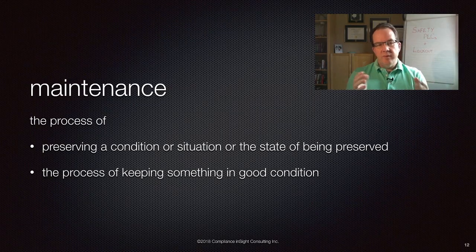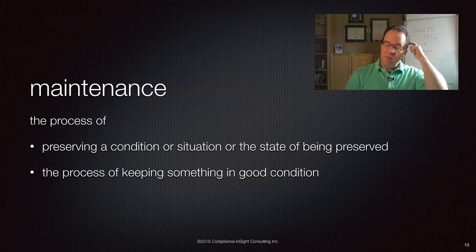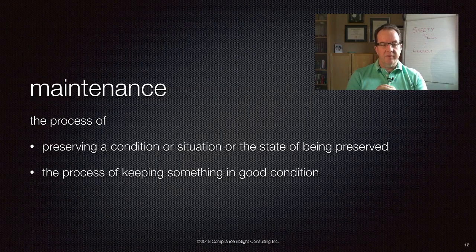When it comes to minor routine repetitive maintenance tasks that take a short amount of time and minimal tools, then using the machine's interlocks is often enough. That short time frame I talked about is usually considered to be 15 minutes, maybe up to 30 minutes. Really anything longer than that is too long. And you'll see when we look at the calculations that I'm going to show you at the end of this video a little bit about why that's true. So basically anything longer than that is really starting to push the envelope.